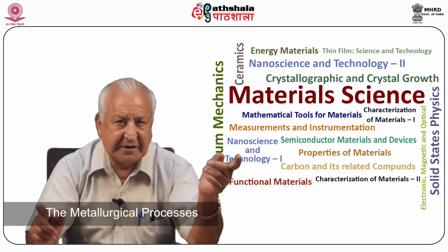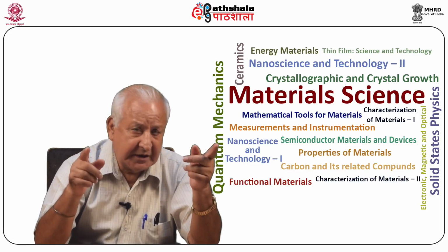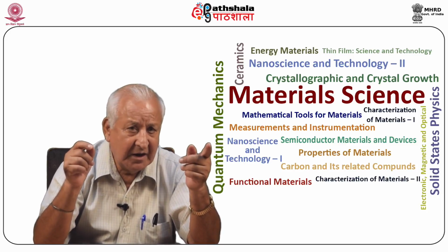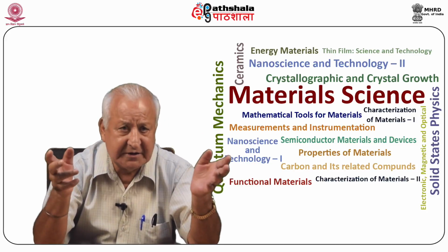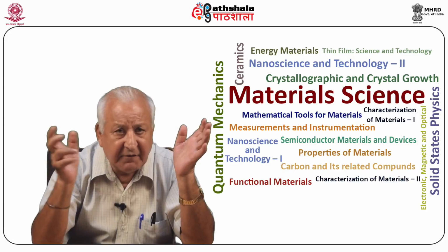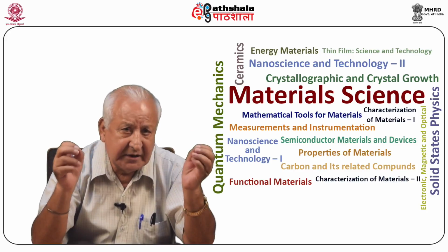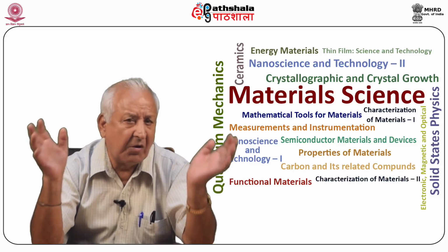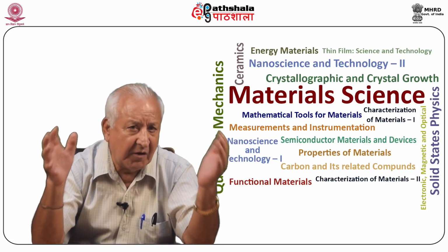The metallurgical processes, including annealing, heat treatment, sintering, and quenching, assume great importance in tailoring the properties of materials. The growth of single crystals, either from polycrystalline or amorphous solids, has certain advantages and some disadvantages. The advantages are its simplicity. Secondly, it is necessary to anneal the sample. Thirdly, possibility of avoiding contamination as no solvents are used and the sample has very limited area of contact with foreign materials.